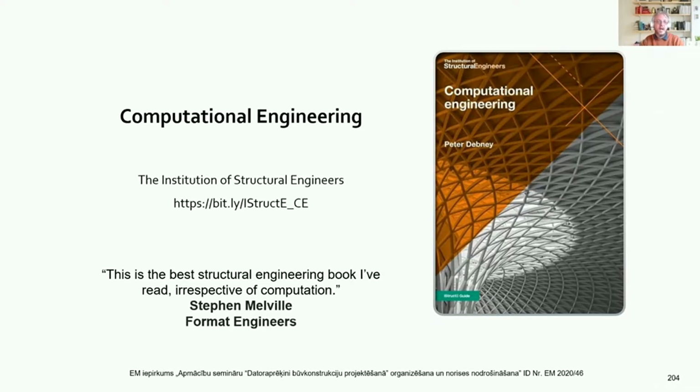it's not a problem. In general, if your software can do tapered elements, then use tapered elements, though you still need to break it down into small pieces. If your software does not do tapered elements, then you'll need to use normal prismatic sections, and you just vary the section according to the average stiffness in each bit.